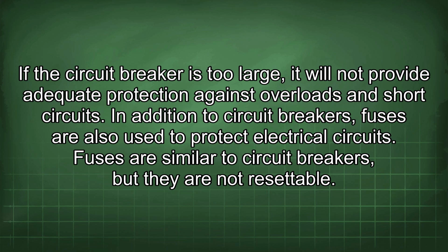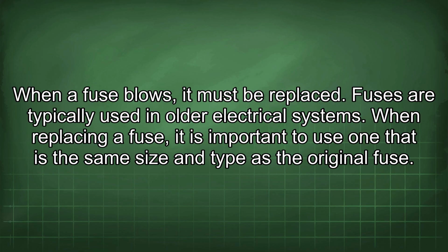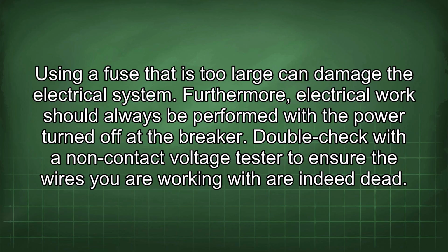In addition to circuit breakers, fuses are also used to protect electrical circuits. Fuses are similar to circuit breakers, but they are not resettable. When a fuse blows, it must be replaced. Fuses are typically used in older electrical systems. When replacing a fuse, it is important to use one that is the same size and type as the original fuse. Using a fuse that is too large can damage the electrical system.